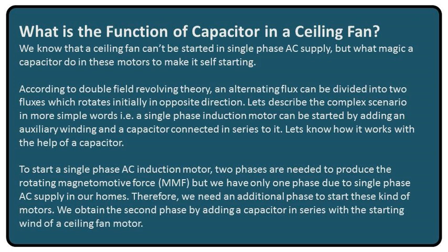To start a single-phase AC induction motor, two phases are needed to produce the rotating magnetomotive force, MMF, but we have only one phase due to the single-phase AC supply in our homes. Therefore, we need an additional phase to start these kinds of motors. We obtain the second phase by adding a capacitor in series with the starting winding of a ceiling fan motor.